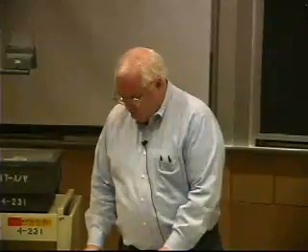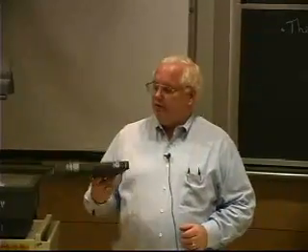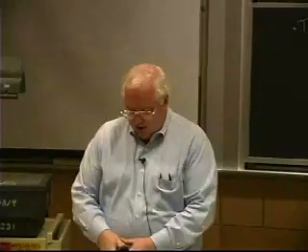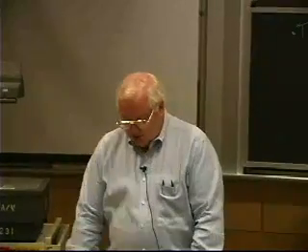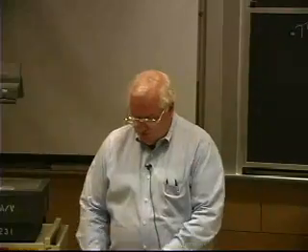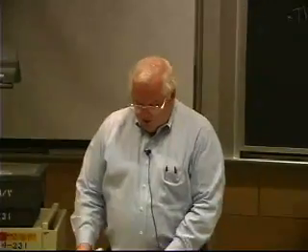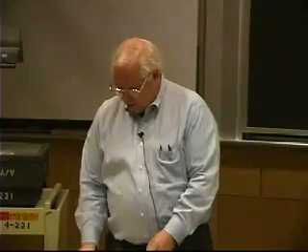But to give you some idea of what to look for in X-rays, there are standard books. I've got about a half dozen of these. There are probably about 20 or more of these things from ASTM, and each one of them they'll sell you. This is one of the smaller ones. They'll sell you this for probably $300 or $500. The bigger ones they'll sell you for about $1,000 or $1,500 a piece. But it's reference radiographs, for this one, for inspection of aluminum and magnesium castings, and there is an ASTM standard, E505. So they give you a copy of the standard. That's wonderful. That's worth a couple bucks.